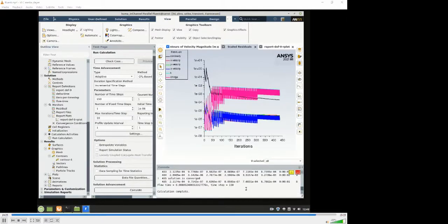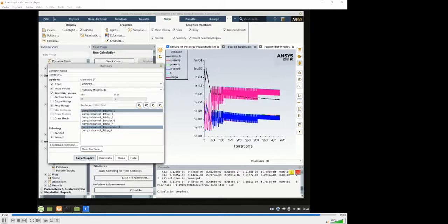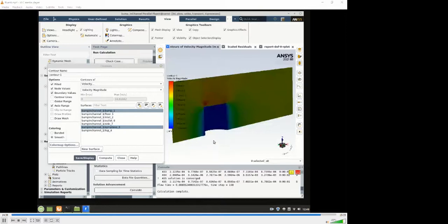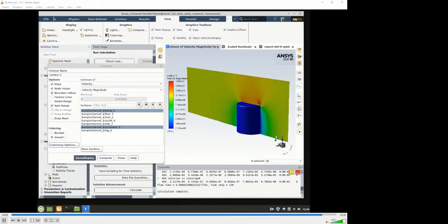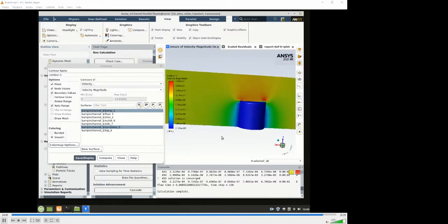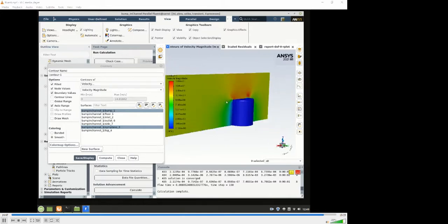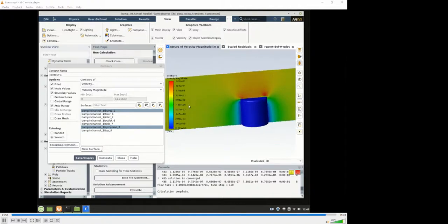We've now finished this phase of the calculation, but as you can see, the flow time has not advanced very much, and that is a typical problem with transient calculations. You only do transient calculations when you hope to learn something from that. So it's still in the early phases of developing a solution, but if we leave this to carry on time stepping, it will develop a flow field behind this obstacle with all sorts of interesting structures in it to illustrate the recirculation, separation, and vortex shedding.